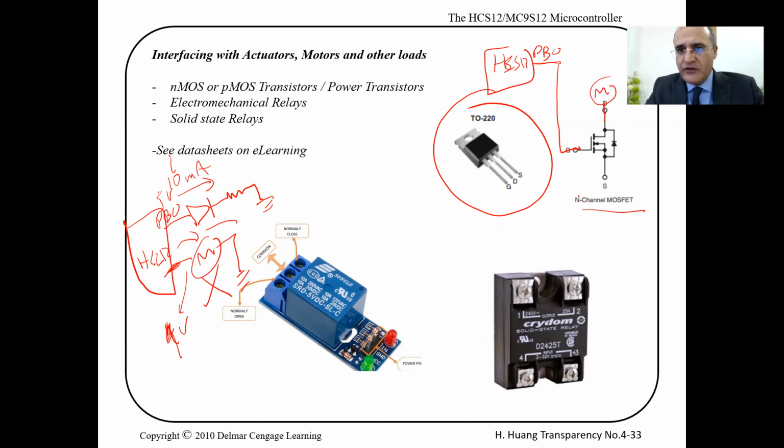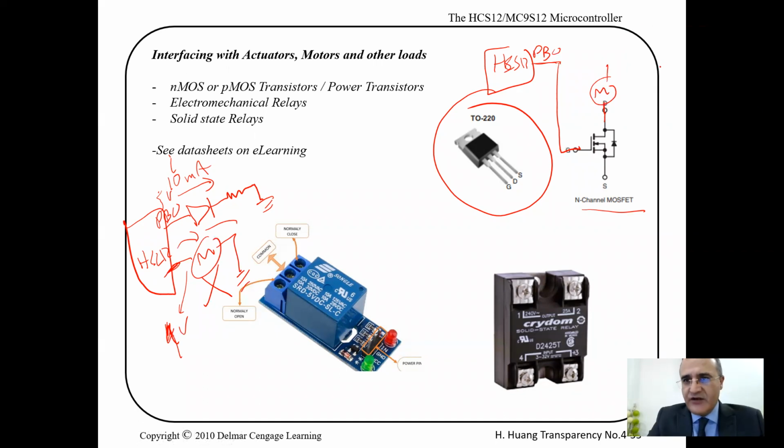One side of it connected to the drain, the other part to the external voltage source, which was, in my case, a 9-volt battery. I took the positive part here and the negative part of the battery to the source, and the microcontroller has a ground pin, and we have to have the same reference. So the voltage drop between the gate and source has a reference different than the reference of the voltage you write on the pin. So you go and take this and connect it to ground, common ground.